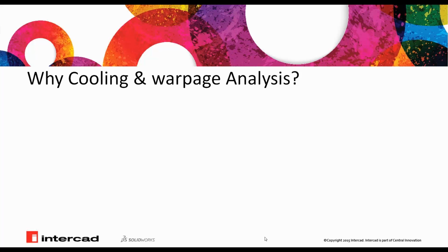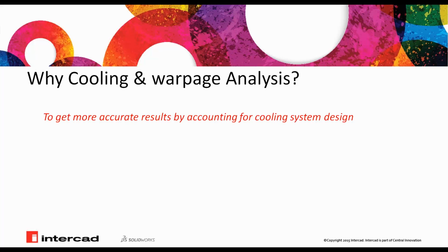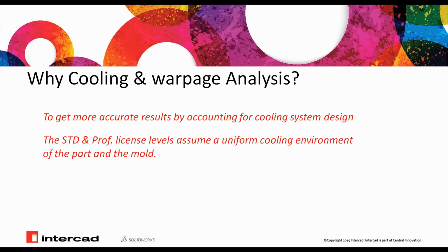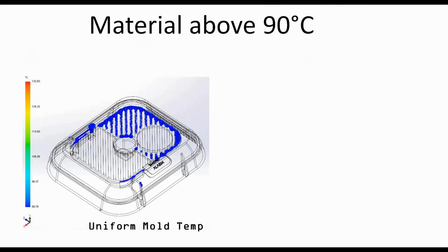And this will take us to why we need to do cooling and warpage analysis. The answer is to get more accurate results by accounting for cooling system design. You may have noticed that the Standard and Professional license levels assume a uniform cooling environment of the part and the mold, so they don't account for your cooling system design.